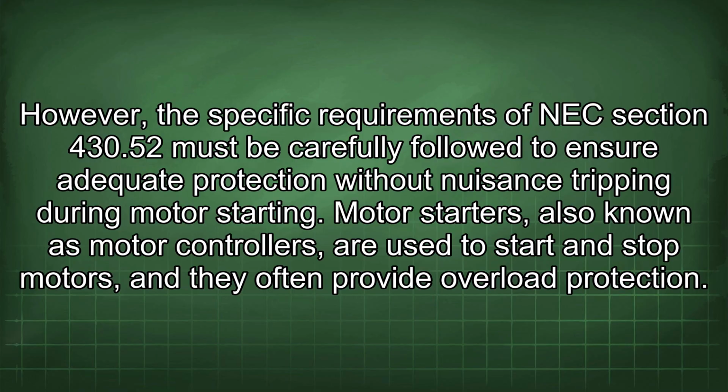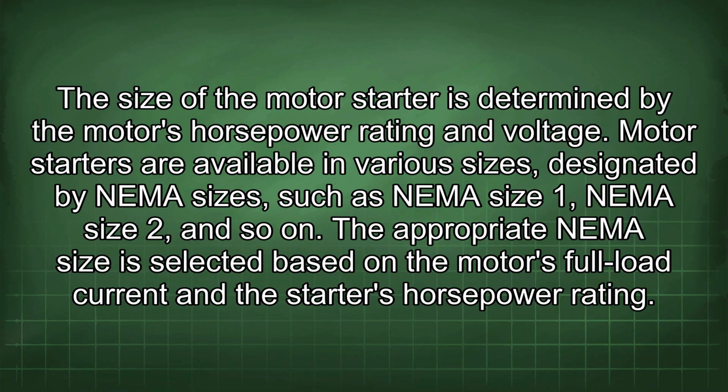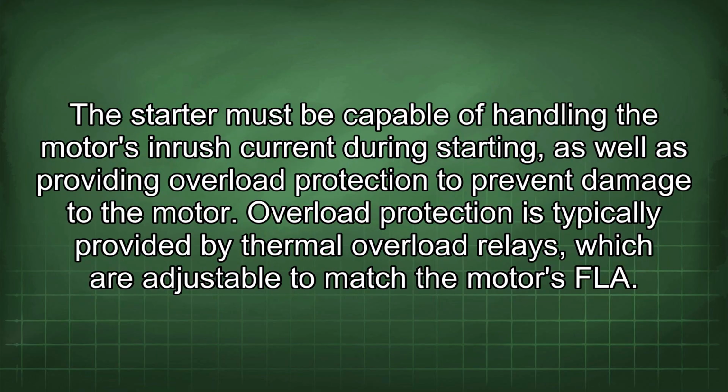Motor starters, also known as motor controllers, are used to start and stop motors, and they often provide overload protection. The size of the motor starter is determined by the motor's horsepower rating and voltage. Motor starters are available in various sizes, designated by NEMA sizes, such as NEMA size 1, NEMA size 2, and so on. The appropriate NEMA size is selected based on the motor's full load current and the starter's horsepower rating. The starter must be capable of handling the motor's inrush current during starting, as well as providing overload protection to prevent damage to the motor.